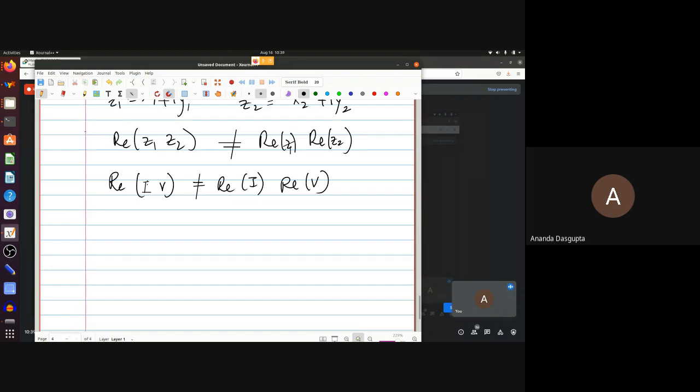What you will do is linearize the circuit. You will take small signal approximations so that the actual complex nonlinear circuit is replaced by a small signal linear equivalent. The whole point of carrying out Taylor series and keeping only the first order terms is that you're linearizing the problem. In that approximation, using this kind of complex currents and voltages makes perfect sense.